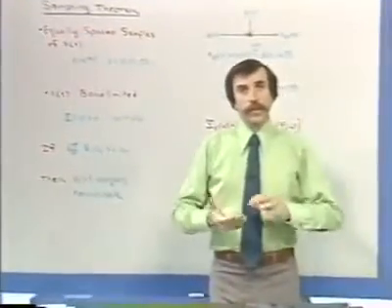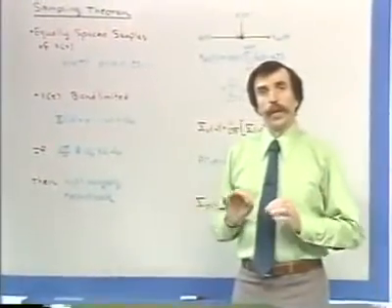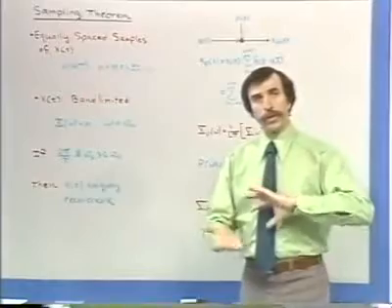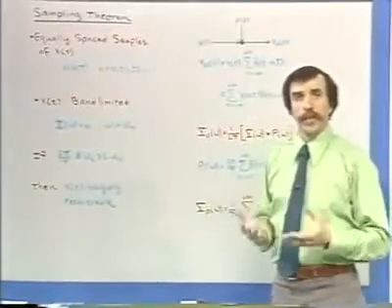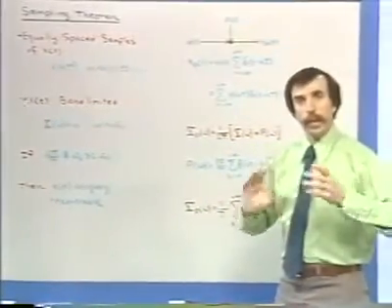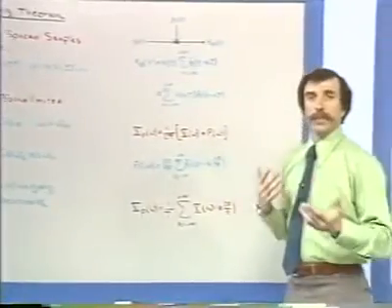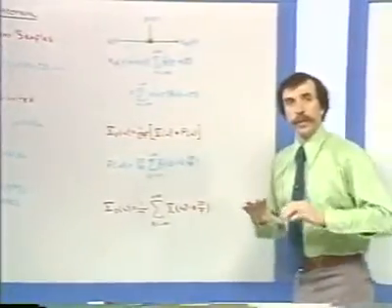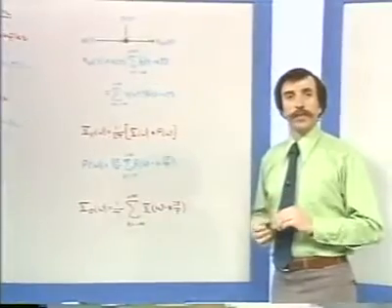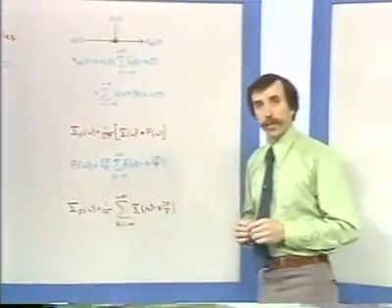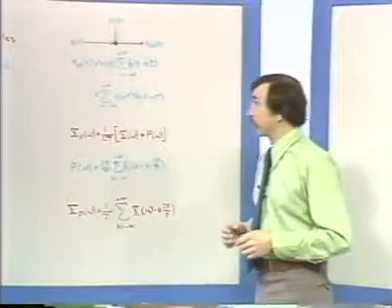The sampling theorem essentially was derived by observing that sampling could be done by multiplication or modulation with an impulse train, and it developed by examining the consequence of the modulation property in the context of the Fourier transform.